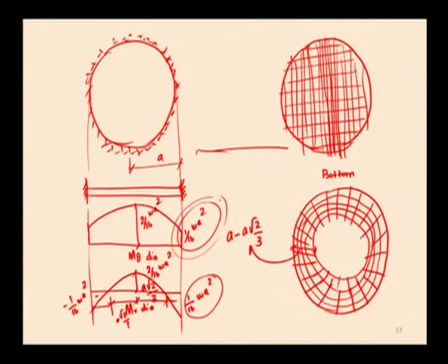So, here when you take the cross section of the slab, this is the cross section of the slab, partially fixed at the ends, and this is the radial moment reinforcement at the bottom, that is along both directions of the slab. And in order to resist the radial moment at the top, since it is fixed, there is a negative moment at the top.